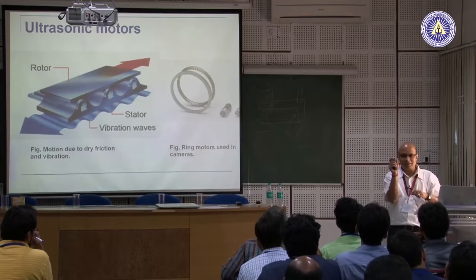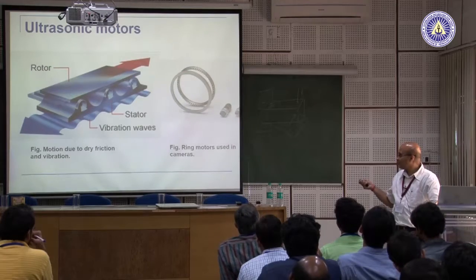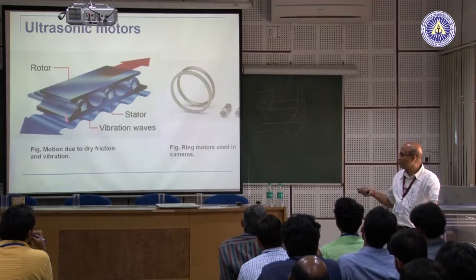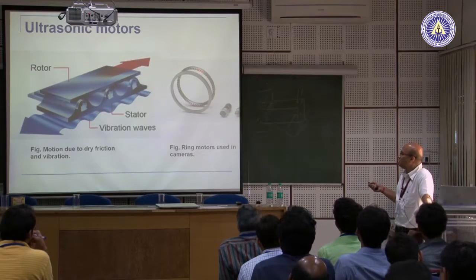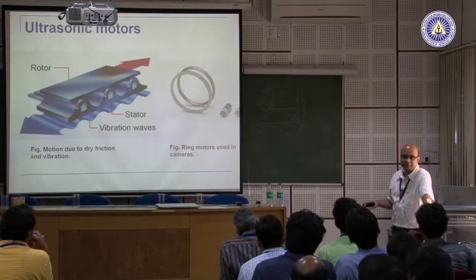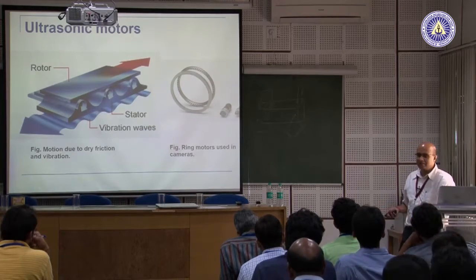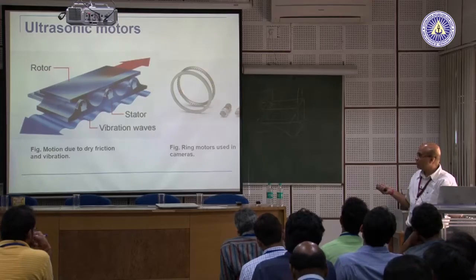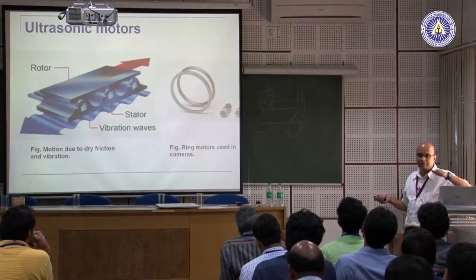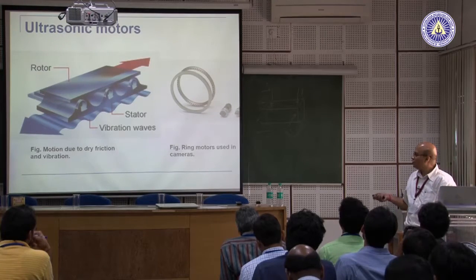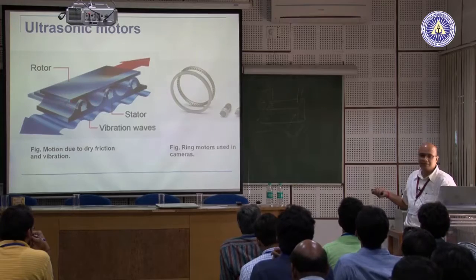The actuation mechanism there is this kind of mechanism. It is an ultrasonic motor. Again, because this is piezo, it does not get affected by the size effect. So, you can make it very small, it will still work. And these are not very expensive, they are very strong. They are strong because there is physical contact there. Only by giving a charge at a particular frequency can you rotate this.